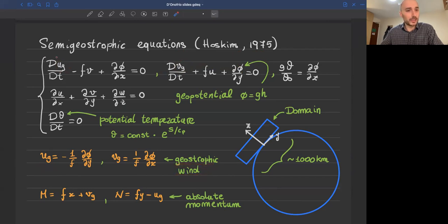And this special treatment for the acceleration term is, here is missing the acceleration term, as you can see. The special treatment takes account of the fact that this kind of flows are dominated by gravity and the Coriolis force. This is the Coriolis force, okay? And this is gravity, which of course only appears in the vertical component of the momentum balance.